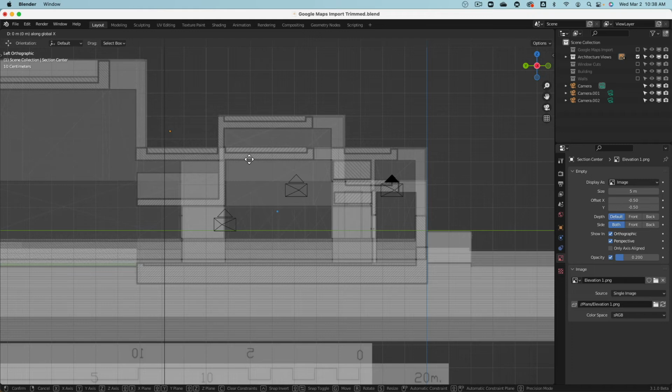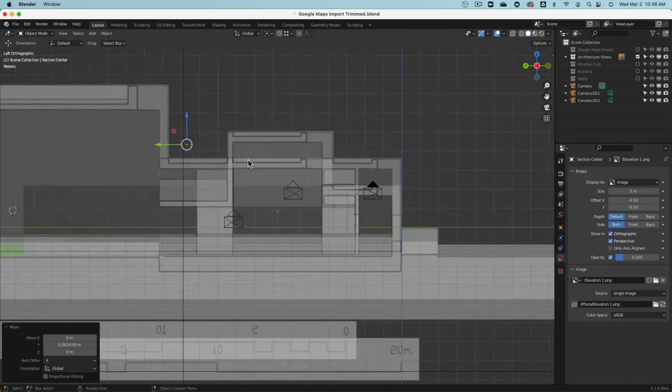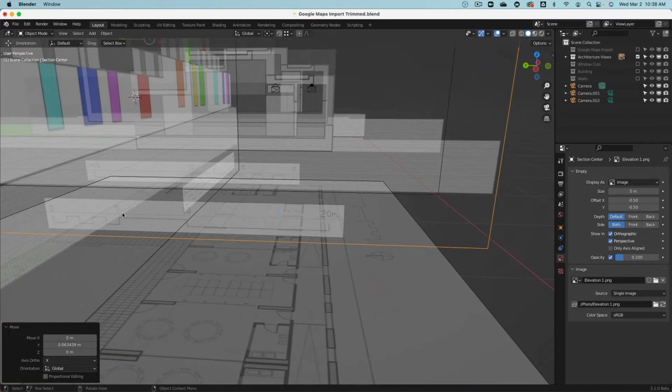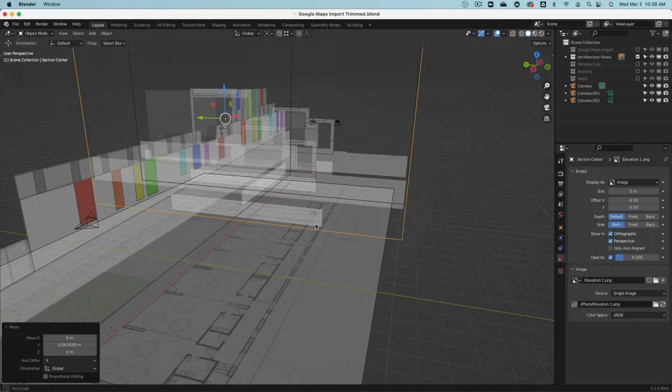And as you can see here, I can fine tune, for example, the position a little bit better. Because these images also have a scale on it, I was very capable of scaling these images to the correct scale. And the trick I used was simply I made a 20-meter long geometry and scaled the images till it fit this 20-meter long geometry on the scale reference.